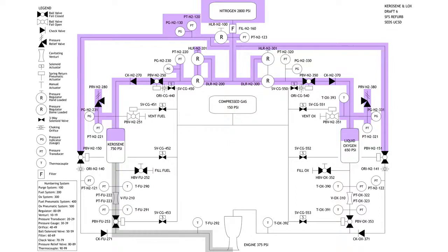So now you slowly reg up your liquid oxygen to 650. And so this pressure-fed system is designed in such a way that you will have a constant 750 or 650 psi boot pushing down on top of your propellants. On our old system, what we're having an issue with is that we're not filling up that gap of the propellants leaving with that pressurizing gas fast enough. So instead of staying at that constant 750 or constant 650, we're just going from like 750 and draining slowly to like 450, 250 until we run out of helium. And so you don't want that.